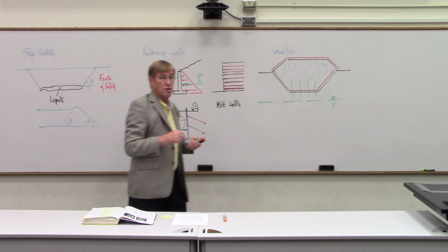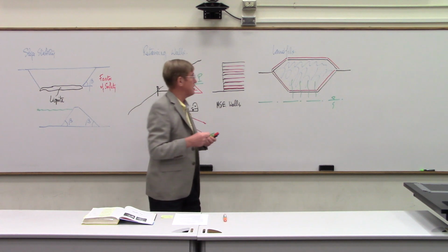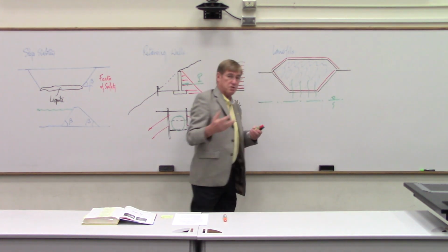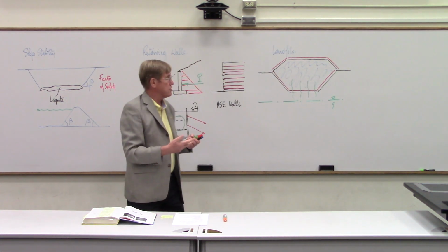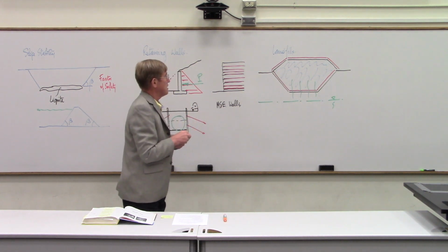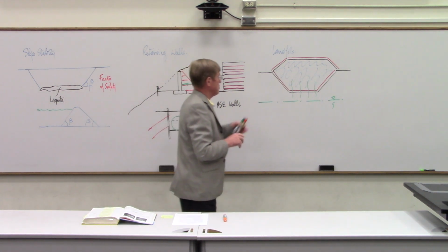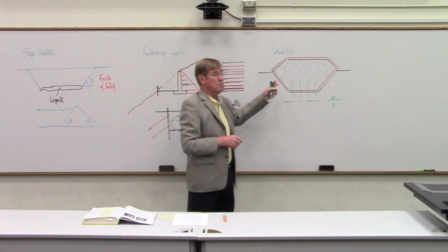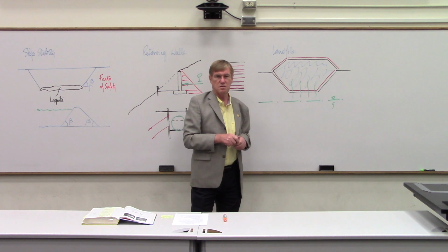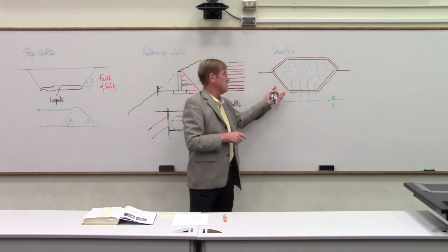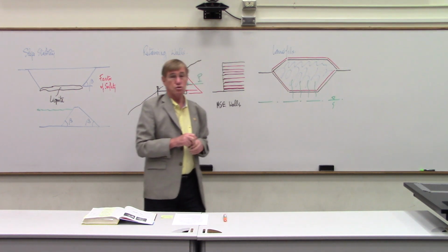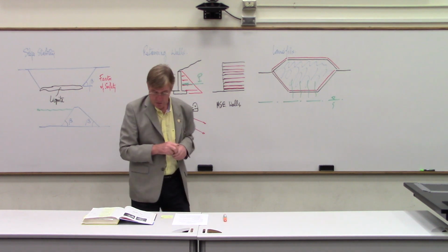And if it does, we have a way to collect this leachate. Below the liner, you would have a leachate collection system, so that you could pump out what little went through the landfill, and then we can be sure that we don't have an intrusion. But that's the most recent way we do these things. Landfills have been around for dozens and dozens of years, and I can assure you that 100 years ago, we didn't have the kind of control that we have now for those landfills.